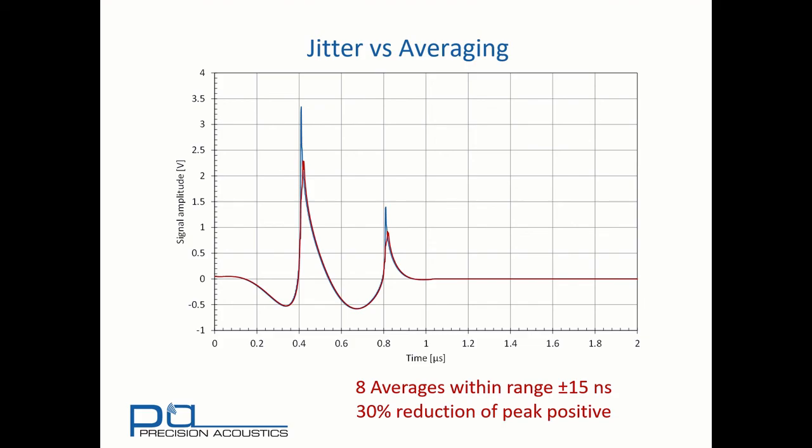This can also happen if we have a situation where there's mechanical vibration in the system mounting the hydrophone. And as the hydrophone moves in an axial direction, you can find a small amount of wobble. Therefore, one of the things that's often recommended is, if we've moved a hydrophone in an axial direction, wait a few milliseconds or even a few hundred milliseconds, depending on the inertia of the system, before one starts making acquisitions.